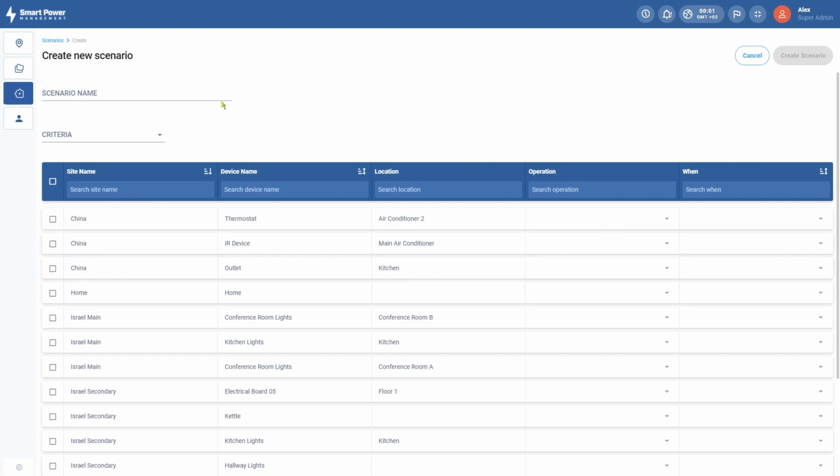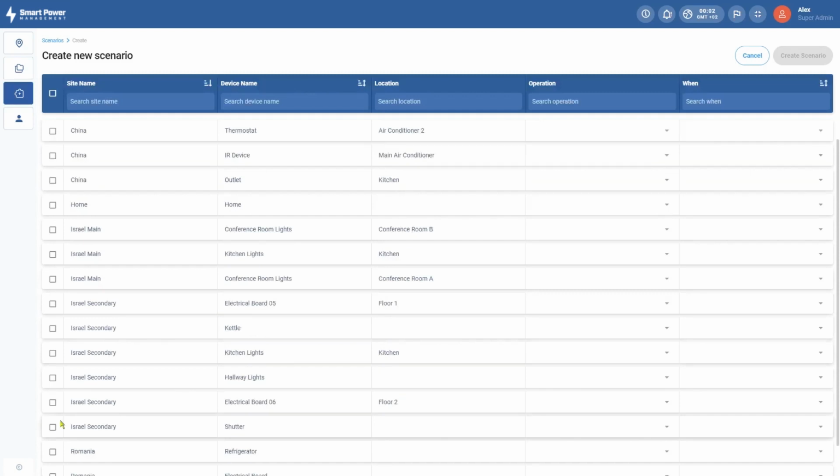Let's assume we have a temperature sensor in our home and some appliances, some smart plugs which control the air conditioning or maybe heat-emitting devices like a TV set, and we're away from home. We can select heat when away based on temperature from this sensor, and if it's higher than 27 degrees Celsius and we're away from home during the weekend or maybe during working days when at work, if this criteria happens, if the thermostat, the sensor, detects that the temperature is higher than 27 degrees, assuming this smart plug is attached to the air conditioning system in the home, we can turn it on immediately.